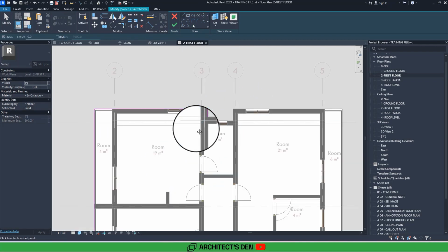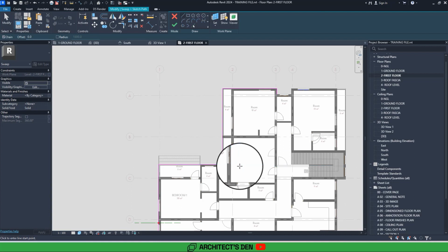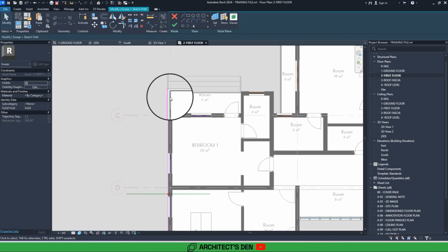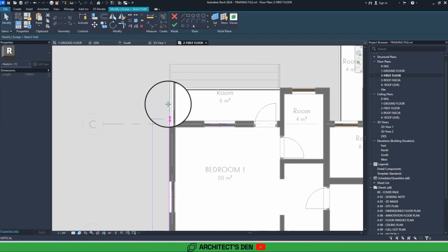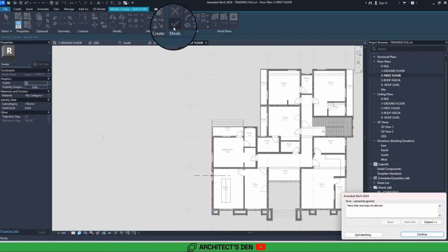So this is a cantilever already, so I don't even feel it's very necessary running the protrusion around a cantilever, because the cantilever is already cantilevered. So, it's easy to make a change there. So I can just drag this line, stop it somewhere here, and then click on OK.